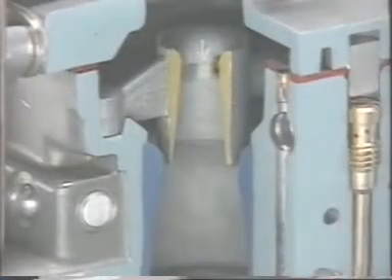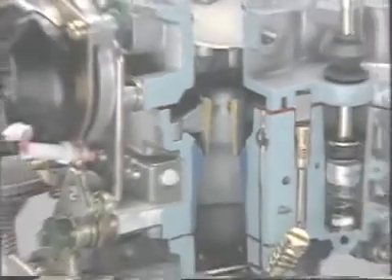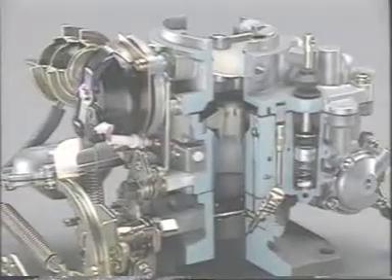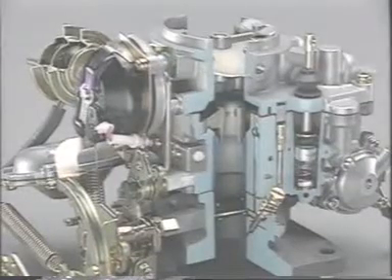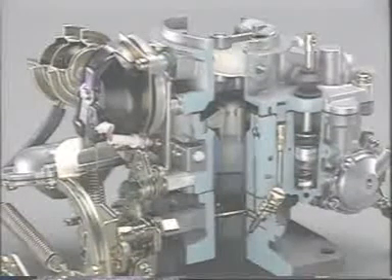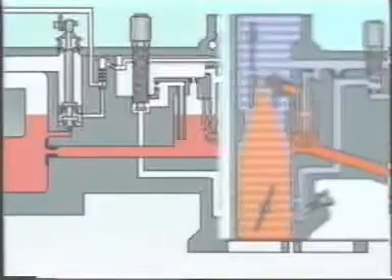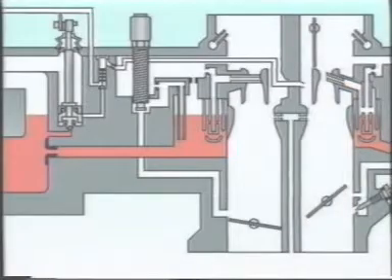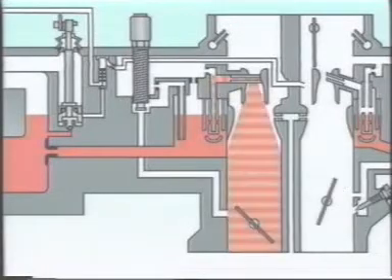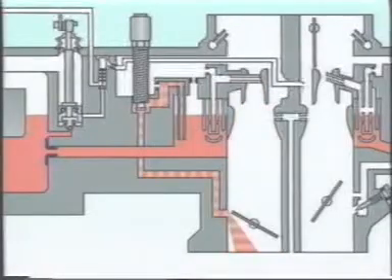This is how the air-fuel mixture is regulated during idling at low and medium speeds. However, this alone will not produce the power needed during high-speed operation. This is why the double-barrel carburetor has a secondary barrel. The construction of the secondary barrel is basically the same as that of the primary barrel. It has a high-speed circuit, which is its main circuit, and a low-speed circuit which prevents the mixture from becoming too lean when the throttle valve opening on the secondary side is small.